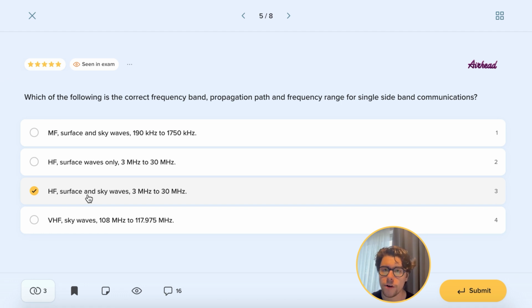So remember for your exams that VHF will be line of sight. It's also used most often for comms when flying inland. HF will be the preferred communication band when flying long haul because its increased distance and frequency is able to jump or bounce off the ionosphere.